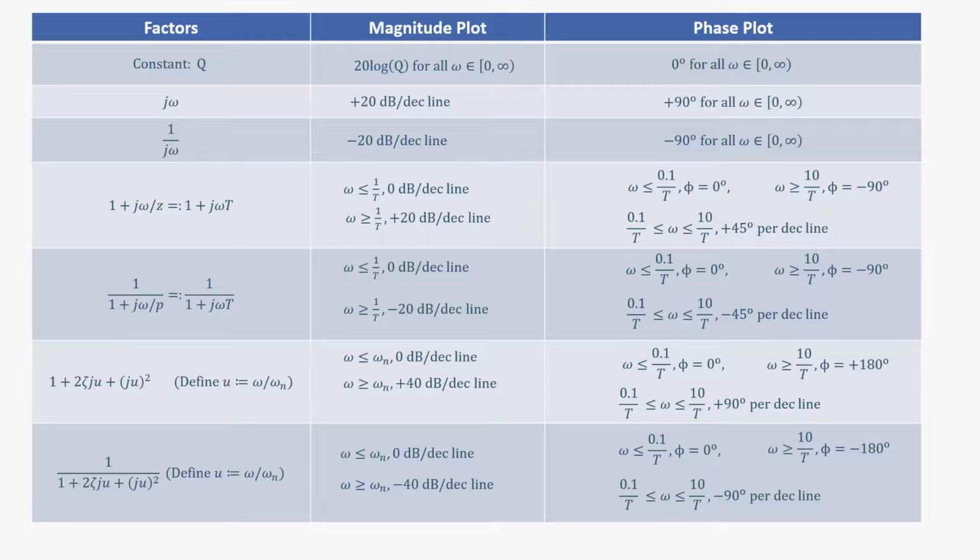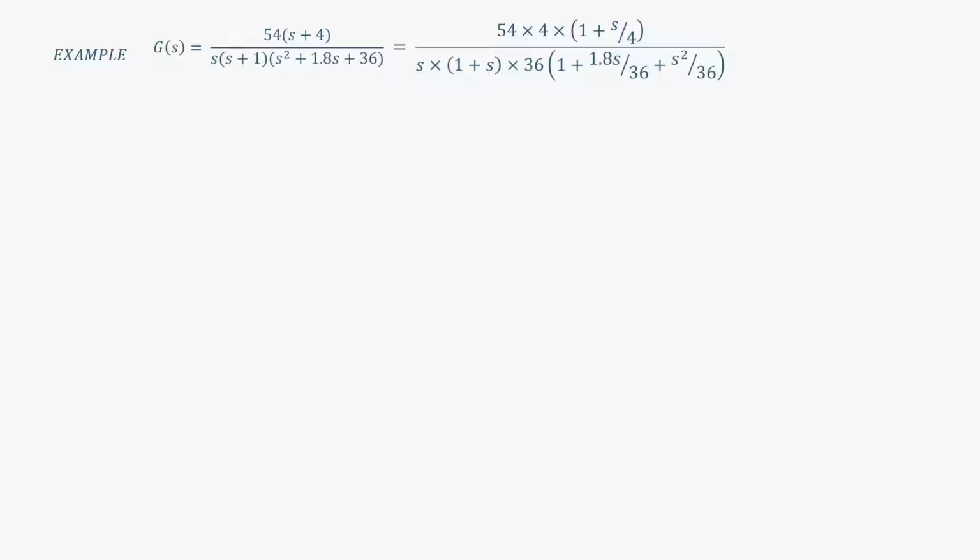So, I will go ahead with only one example and then I will add a few in the assignments for you to practice. So, suppose this is the example given to you, you have a transfer function given to you. Now, of course, the question is how do I find this transfer function? This you can find out with one of the methods that we have already discussed, basically using the step input and then feeding it into the system and then trying to use the functions that we had shown in one of the lectures and try to estimate what is the transfer function of the system.